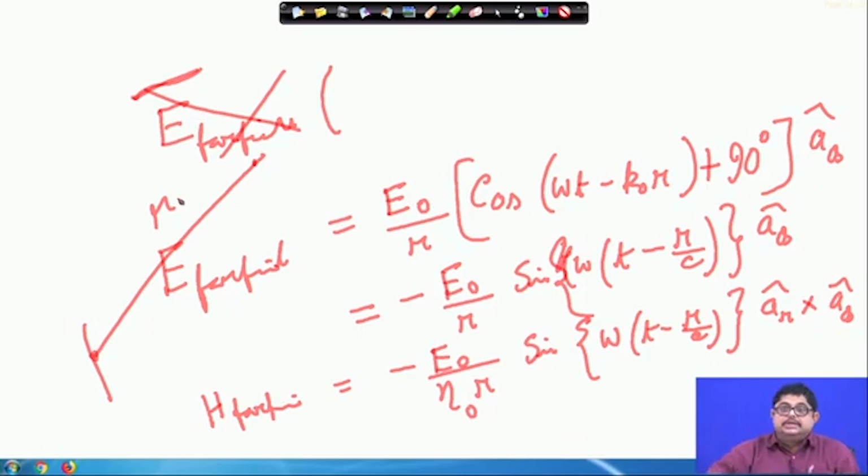They always show a radial flow of power, there is a triplet, locally they are plane waves in the far field, they also have this time delay, and they have the space delay according to the wave that created them, e to the power minus j k naught r by r, and they have all these properties. That is why we studied the current element.